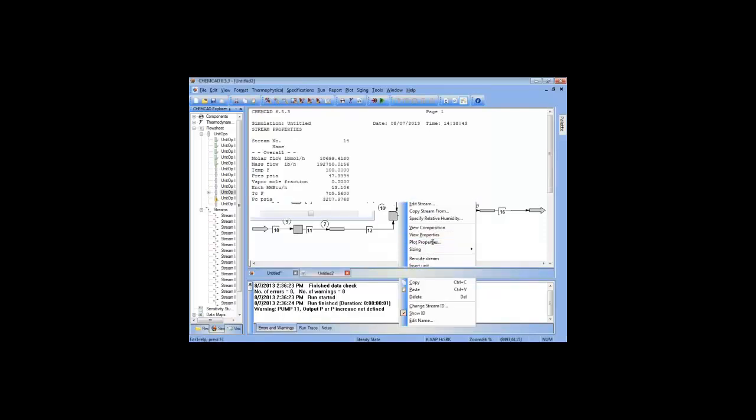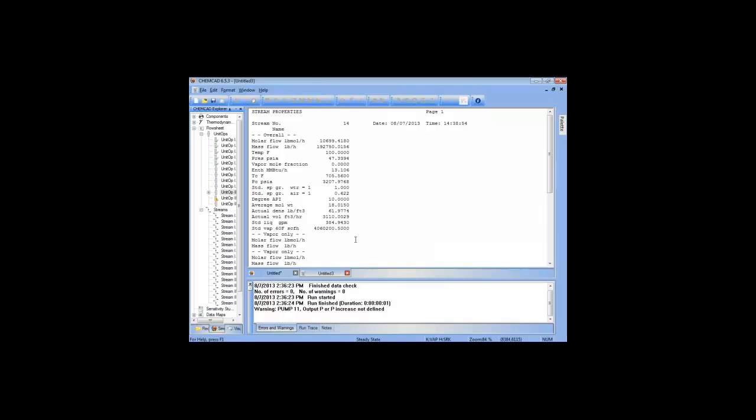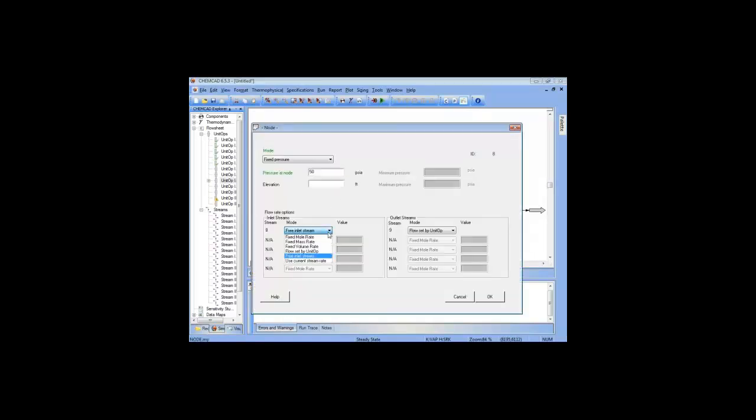So now, since this is not going to a feed or a product arrow anymore, we can't specify the flow right here like we had specified. We can change this back, though, so we know that we've got 384 standard liquid gallons per minute coming through, which is, in properties, 387, I believe it was. So 387, let's call it 388 coming through this branch. So if we solve that, we can set this for volume rate, 388.